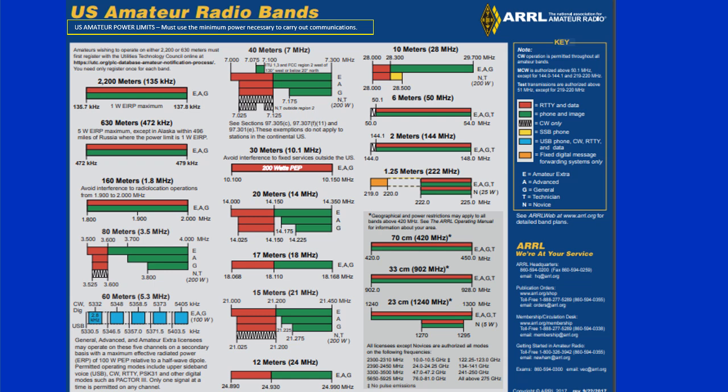This means that if you made contact at 100 watts, let's say, then the person said, you are booming. You're loud and clear. You're like blowing my meter off, so to speak. If you're really coming in, you should automatically then say, I'm going to reduce my power to 50 watts. Can you still hear me okay? Yep. Okay, let's try 30 watts. Okay, you still hear me? Yeah, that's fine. Okay, let's do 30 watts. So technically, you want to use the minimum power necessary to carry out communications.